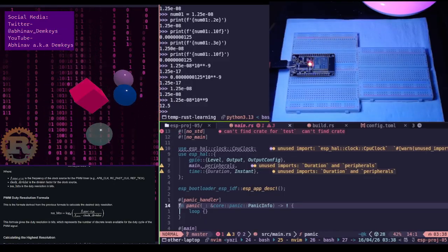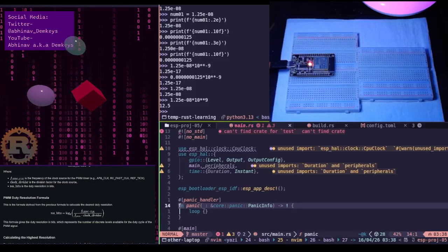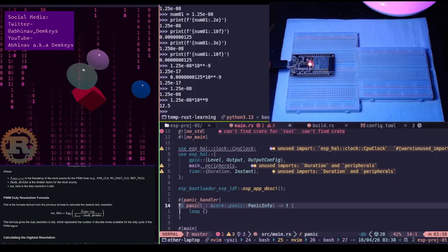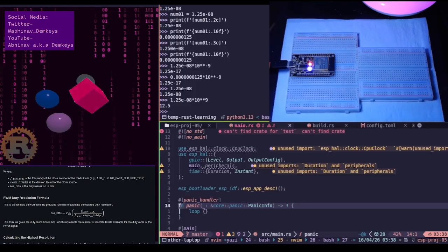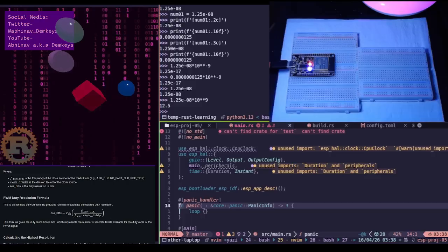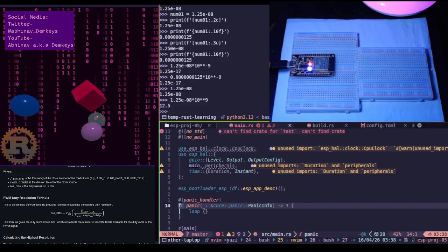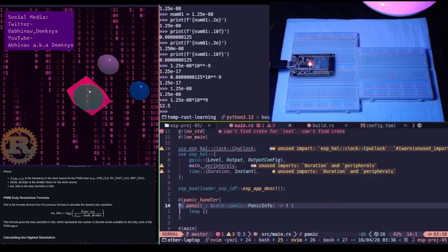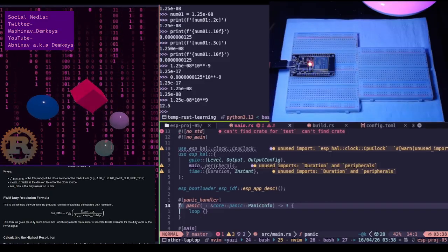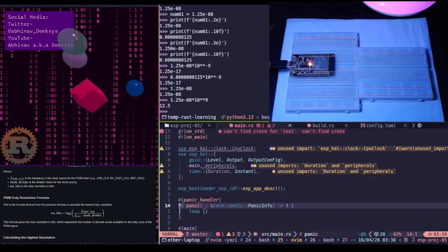And to avoid that, I would have to add a couple of things like a capacitor. That's mainly for filtering the noise, but additionally, to protect from current from one point going into another point where it's not supposed to, I would have to use a diode. And all of this is analog electronics knowledge, right? I don't know any of this, so I kind of feel like